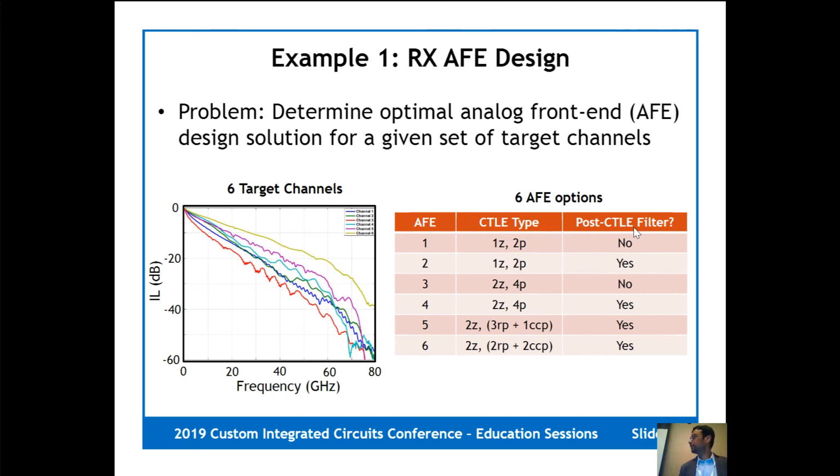I'll ask you one. You mentioned that the crosstalk is much more detrimental for PAM4 at high speeds, the amount of crosstalk noise. That's right. What are link designers doing to reduce the noise? Primarily, the design modifications to reduce crosstalk are channel modifications. There isn't anything that I'm aware of from a circuit side. People are not looking at active crosstalk cancellation, for example.